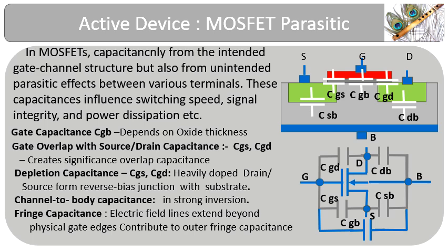CGD provides negative feedback and, due to the Miller effect, increases input capacitances by gm times. Drain and source to body capacitances, CDB and CSB, are created due to reverse bias junctions. In normal application, as sources return to body, the CSB is ignored.